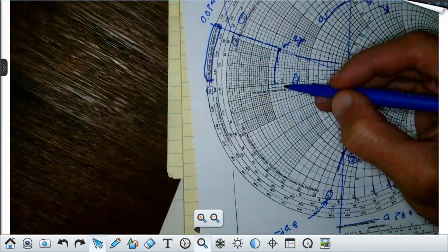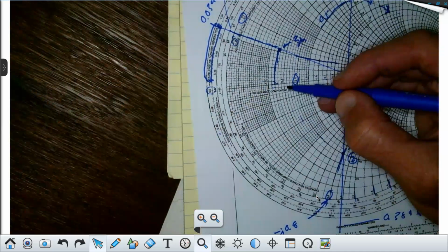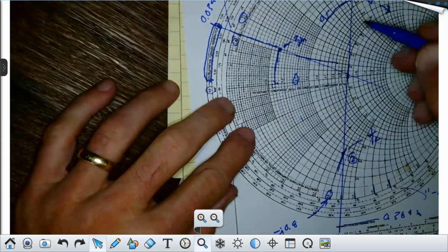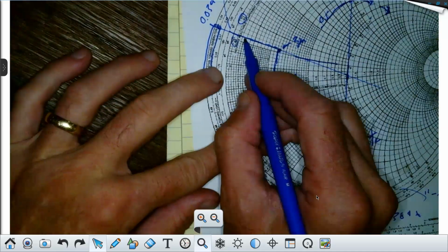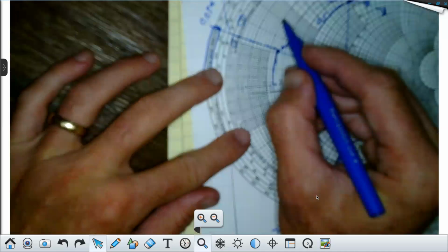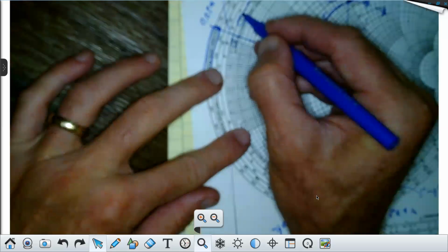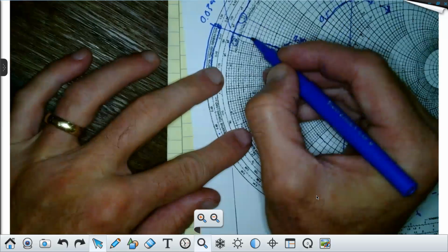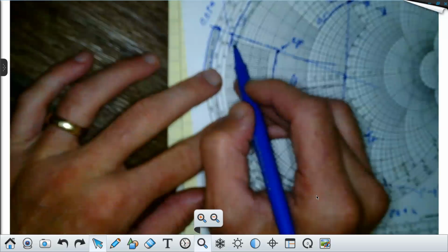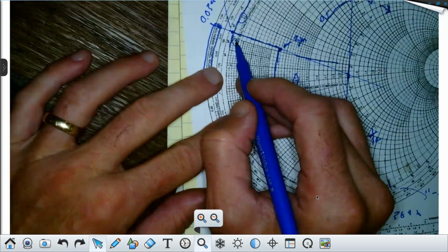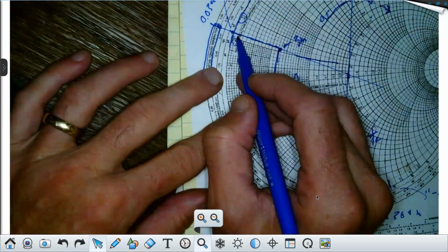I need to know. Carlin, can you? Okay, you can see that, right? Now, take a look at the line that goes perpendicular to it on your Smith chart, not mine, and see where it intersects this line right here. About here, right? And on your Smith chart, if you read this, you should see 0.2 about here, and this will be about 0.22, 0.24, somewhere in there. How many can see that?